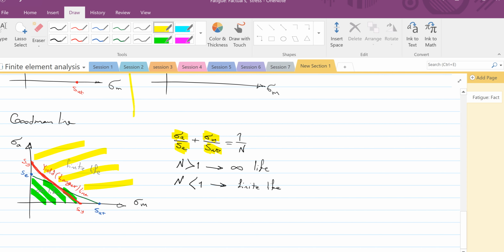And because we need those numbers to be able to solve fatigue, fatigue calculation is a post-processing calculation, not part of the initial calculation. So ANSYS is going to solve all the stress strains and then use those data to calculate fatigue.